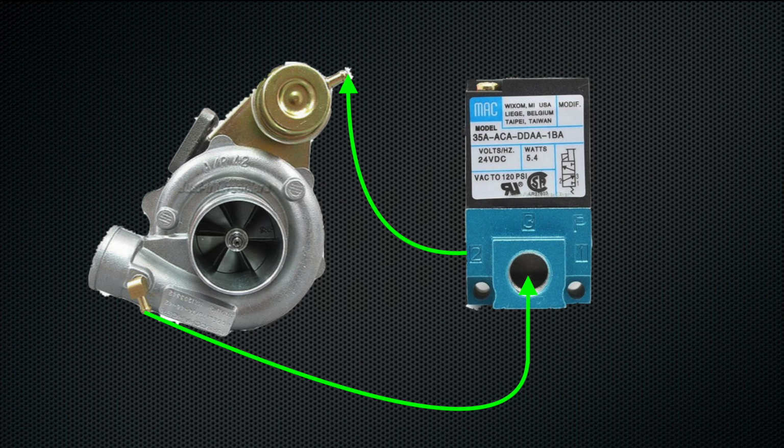So whatever the exhaust pressure is going to be generated in the turbine housing, there's going to be a certain point where it's going to blow open that flapper valve, flapper door, and it's going to start to just naturally bleed off the pressure. But that may be at something like 30 or 40 pounds of boost. So if you have a 10-pound actuator and you just simply remove that pressure reference, that can build whatever the system is allowing itself to build. And that's all going to be hinging upon the exhaust manifold pressure, how high the exhaust pressure gets till it blows open the flapper valve. But it can generate usually 3, 4, 5 times whatever your wastegate actuator is rated at in terms of boost pressure.